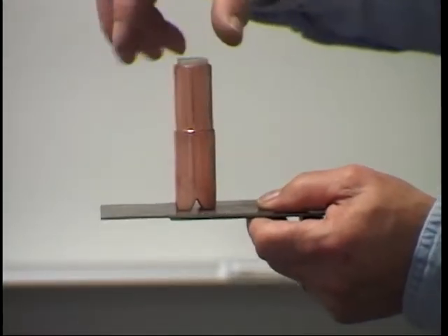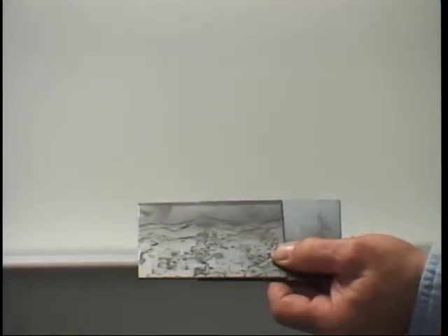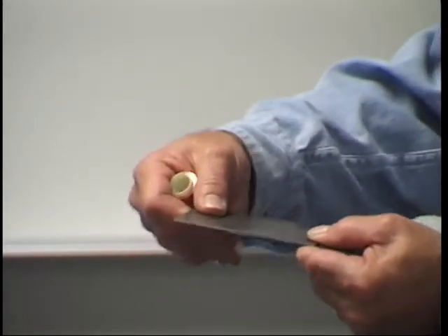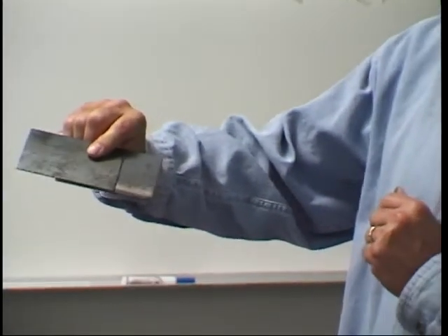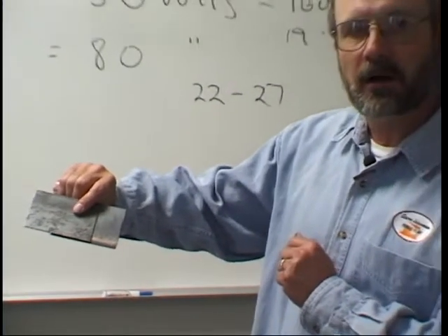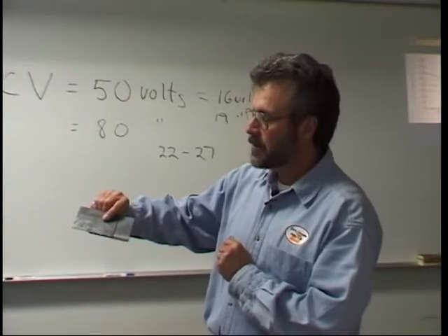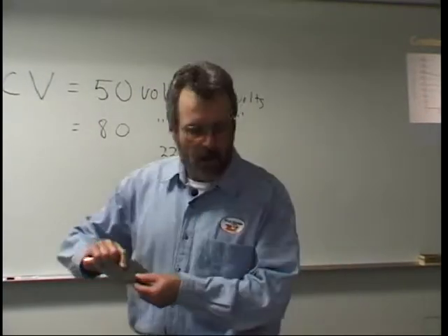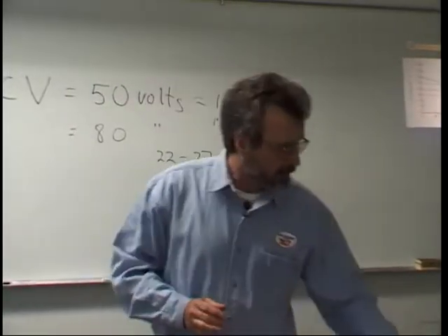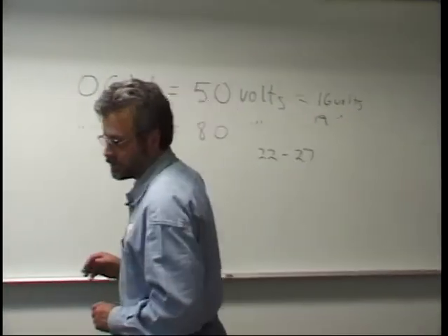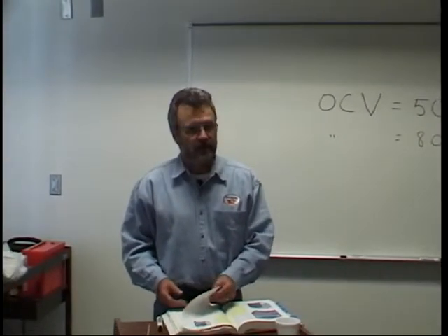Light and smoke and sound is all going to come out. When you pull that away, you're going to have a nice little spot in there, maybe about the size of a dime, and these two things will be joined together. Spot welds are great. Typically, the strength is about 800 pounds. We wouldn't be able to pull those two pieces of metal apart if we were to put a spot weld on there. We'd probably have to get a hammer and chisel and still not be able to get them apart. So spot welding is something that you should be familiar with. It's a very common practice, and that's what the timer control is used for. So that would be a bullet as well. I may ask you a question about spot welds.